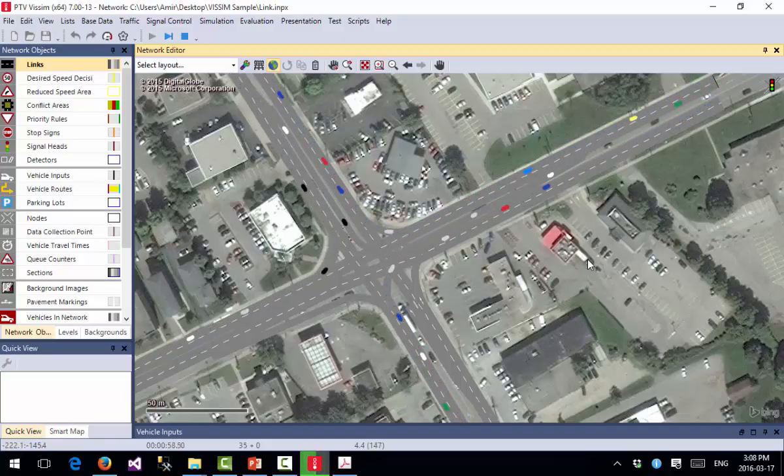You see they are passing each other. They're going through, because these links actually are not connected to each other. So they are like elevated from each other. Not elevation, but as you can see, they are passing over each other, which we do not want to happen. Yes. So we need to define the right of way and some other things. So we need to define right of way for these values. Anything else? Oh, we need to solve the turning movements first. Okay.